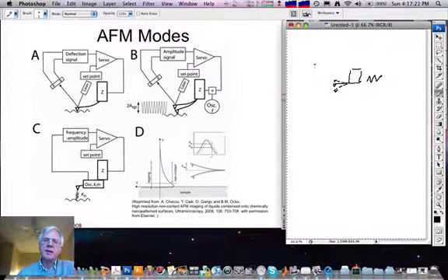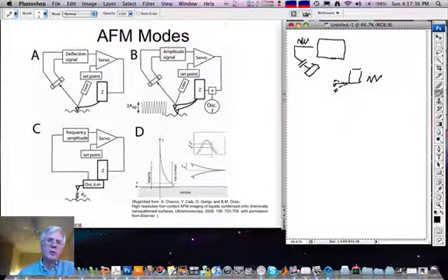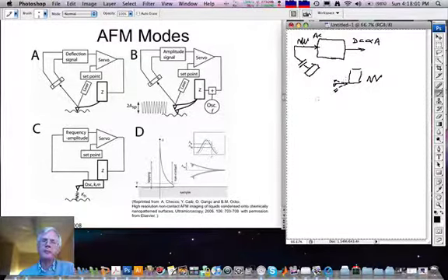And so one picks up in the detector the AC component of the signal, like this. So this is now just purely an AC signal, and then puts it into a circuit that either is sensitive to the root mean square amplitude, or alternately and preferentially is a genuine lock-in or phase-sensitive detector, so that with an AC signal in here, one gets a DC signal that is proportional to the oscillation amplitude of the signal, and then this is fed back into the height of the cantilever so as to maintain the amplitude of operation at the desired set point.